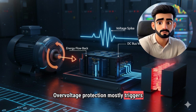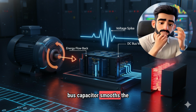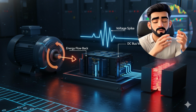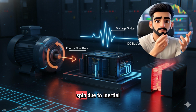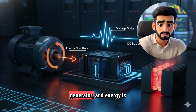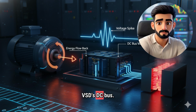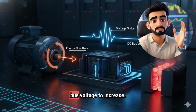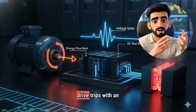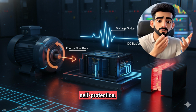Overvoltage protection mostly triggers around the DC bus. You heard in part 1 that the DC bus capacitor smooths the DC. Now think, when the motor is running at high speed and you suddenly give a stop command to the drive, the motor continues to spin due to inertial load. At this stage, it starts behaving like a generator, and energy is pushed back onto the VSD's DC bus. This causes the DC bus voltage to increase. If this voltage exceeds the safe limit, the drive trips with an overvoltage fault. This is the drive's self-protection.